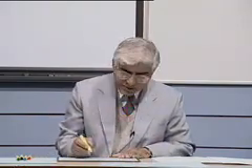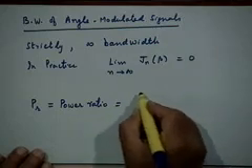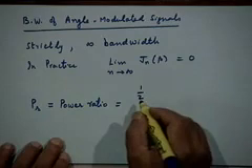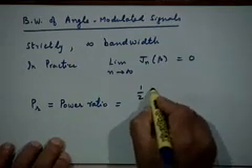Look at the energy in this part of the signal. This is approximating the actual signal, and take the ratio of this energy with the total energy of the signal. So I am calling that either the energy ratio or the power ratio; actually power ratio is a more appropriate term. So what will be the power contained in the 2k plus 1 components that I just mentioned?